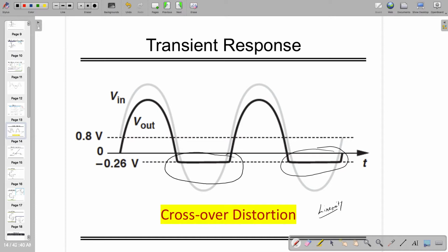for the power amplifier. So if you are using such a circuit, where your overall circuit performance in terms of SNR is very good, and if you add this, SNR is degraded. In that case, if your SNR or the total harmonic distortion is degraded, your output is going to have worse noise performance. So that we don't want. That's why this crossover distortion has to be removed.